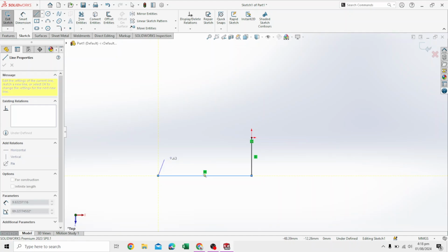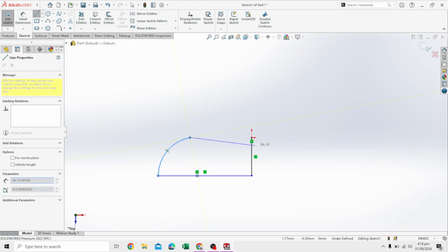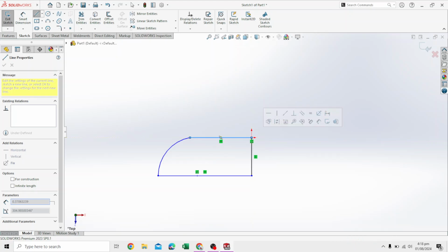But if you take your cursor back to the point where it's attaching to the first line that you drew, it will change it to a curve. See, it's now curving. I didn't select any arc. If you see on the top ribbon, line is still selected, but now it's drawing an arc. We will take this line up to here, in line with this, and then we'll connect this with this to make this kind of geometry.